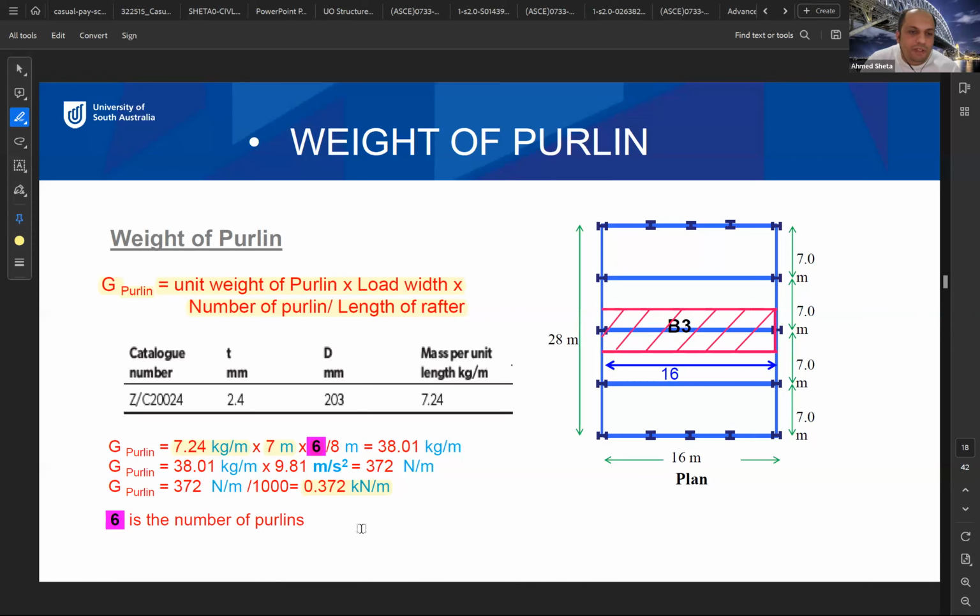And also, I want to advise you to be mindful with the numbers or with the results, because you are doing almost similar spans and similar loads. So the final loads or the final answer should also be close to what you have seen in this example. Okay, so if you find the numbers are very far from here, like 0.0003, something like this, or 10,000 kilo, this means that you have done something wrong in the calculation.